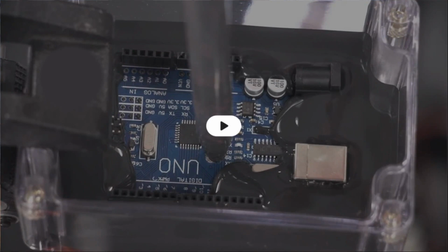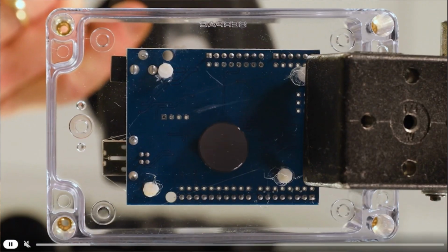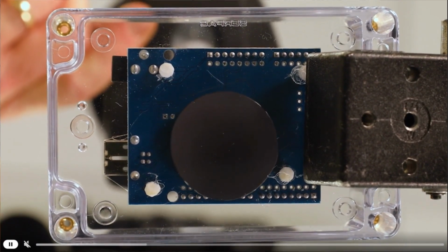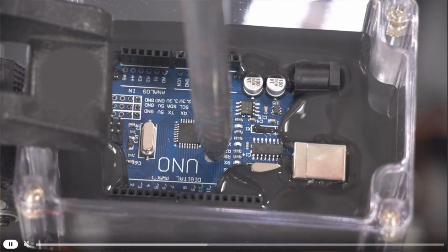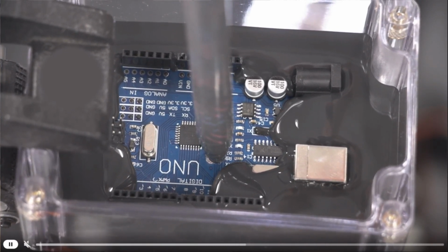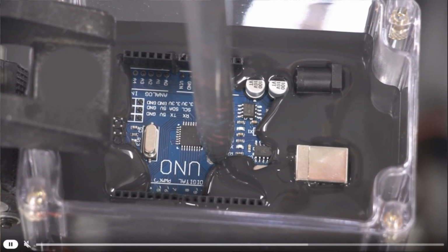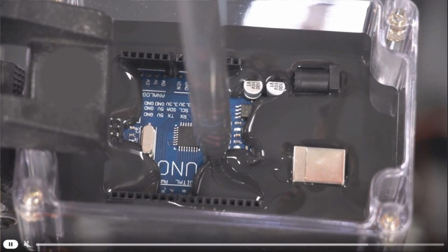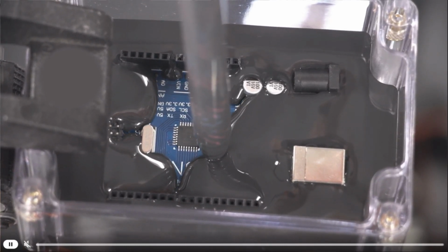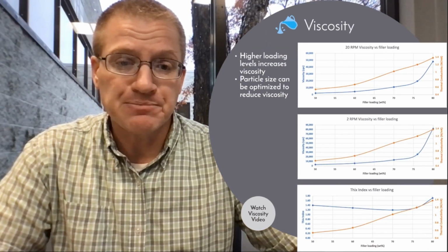So in electronic potting applications, we're worried about how well a material flows in and out of different areas. If you look on here, you see some very small pinholes, some through holes. As this image comes back up to the top, you're going to notice how this flows actually up through those pinholes. So this material was designed to have a high thermal conductivity, but additionally to flow very well and really encapsulate and coat all those different components. That way you have really good contact of the polymer, so you can conduct that heat away very efficiently, okay?